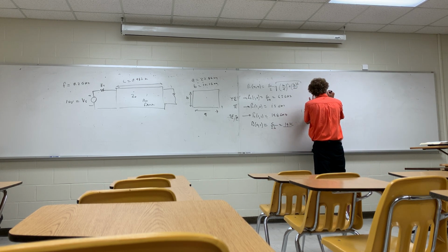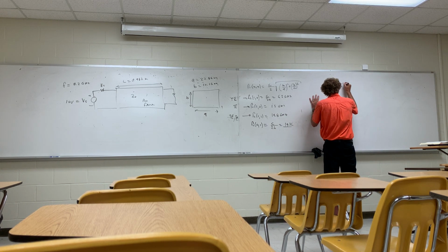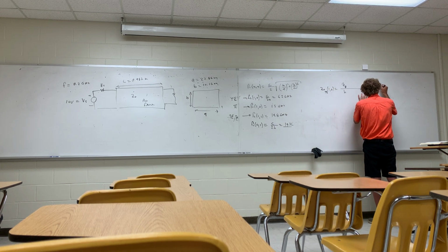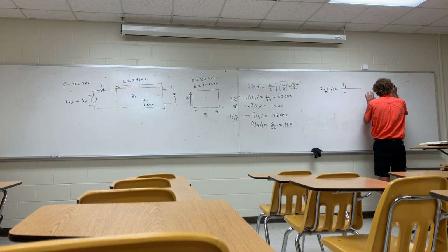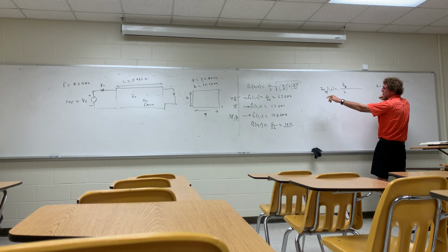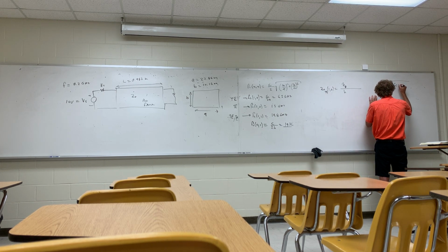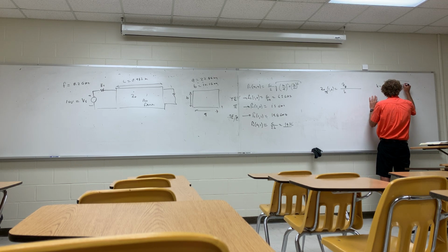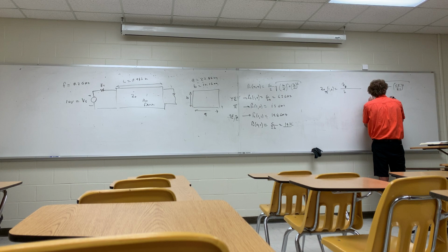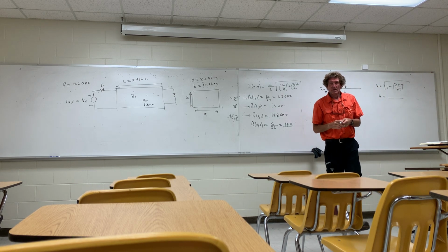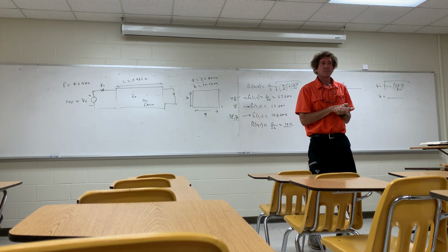For the characteristic impedance for the TE 10 mode, that's gonna be simply the characteristic impedance, and it's really beta naught here, over K, and K is equal to the square root of 1 minus the cutoff frequency, which is, for the 10 mode, 6.5 gigahertz, right? And it's over the operation frequency, which is 8.2, and you have to square that. So can you give me the value of K? 0.610.